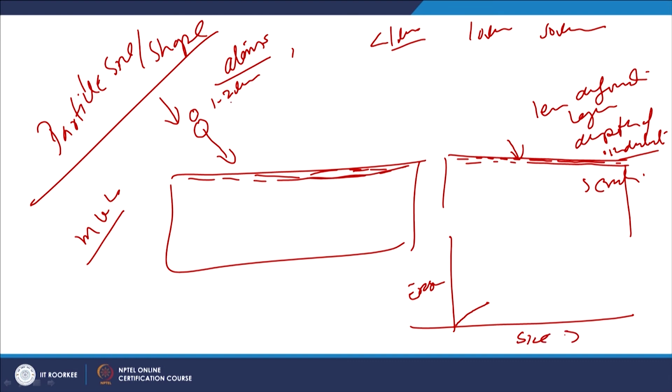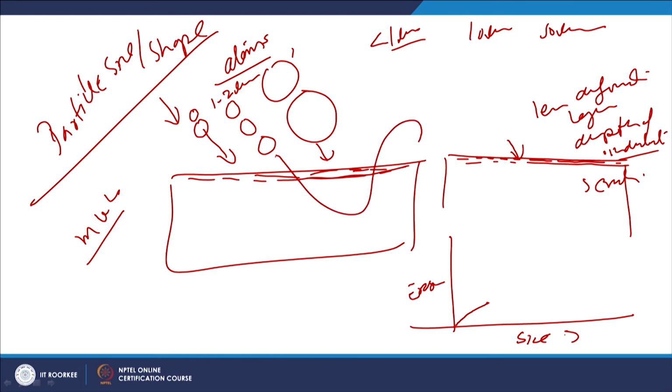When the particle size is increased, say to 10 micrometers or 50 micrometers, the particles are very big, having a lot of kinetic energy, moving at a very high speed, and they impinge on the surface of the workpiece. If the material is soft and ductile, it will cause huge superplastic flow of the material sidewise.